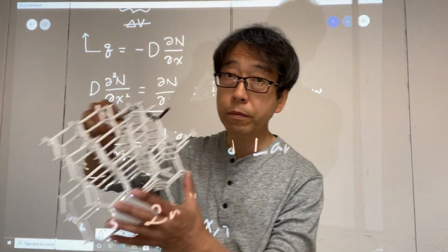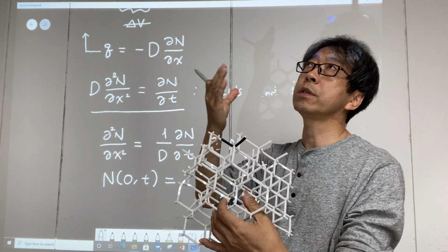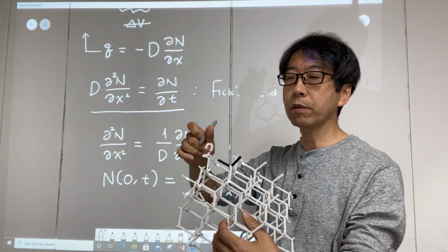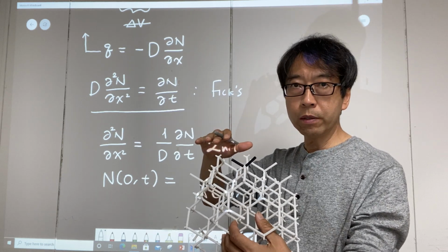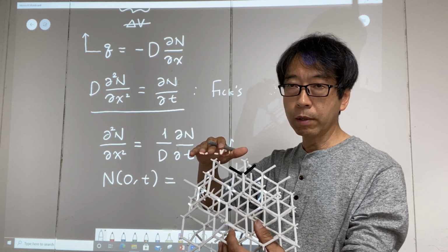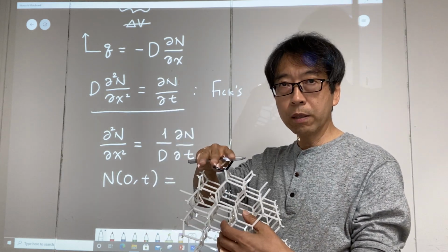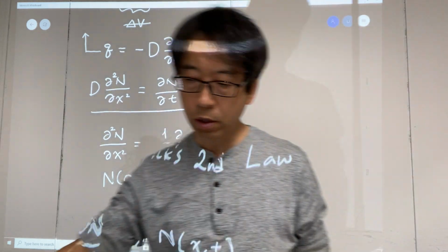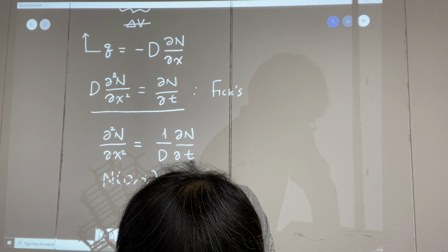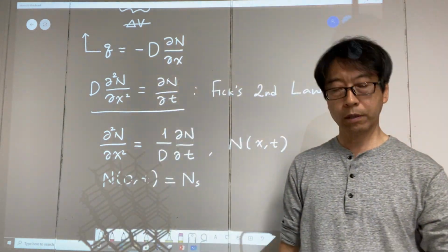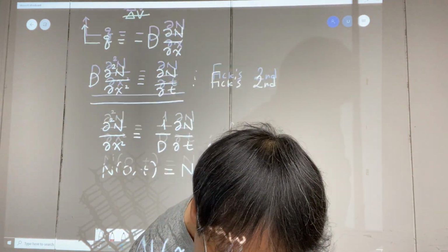At the surface, whatever time it is, we'd like to assume a very simple thing. So you have a surface, and at the boundary, we'd like to assume the simplest case. What is simplest? The concentration of the impurities at the surface just remains constant, right? Isn't that the simplest case? Rather than changing something, let's make it simple. Let's make the surface concentration constant at, for example, N_S, surface. How about that? All right. Well, that's the boundary condition, and the initial condition could be N.